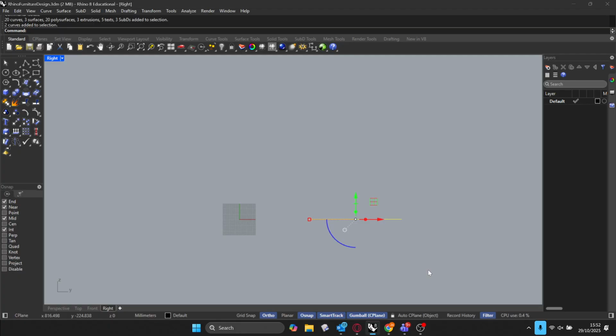Okay? And what I'm going to do now is I'm going to rotate these lines. So I'm going to select them all first, dragging a box over. And one other little tip is if I drag a box from right to left and it goes blue, it'll only select what's inside the box. If I drag a box from right to left and it has this dashed line around it, it will select whatever the box is touching. So it doesn't need to be inside, it's just whatever it's touching. So drag a box over, and now I've selected all of my lines.